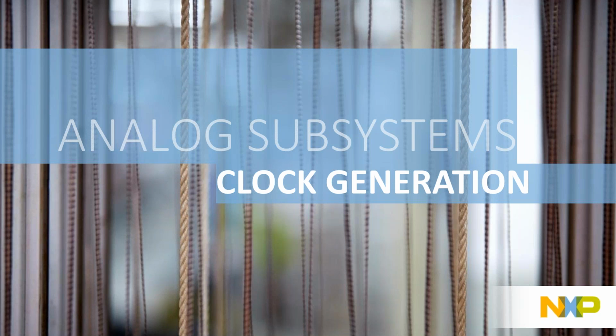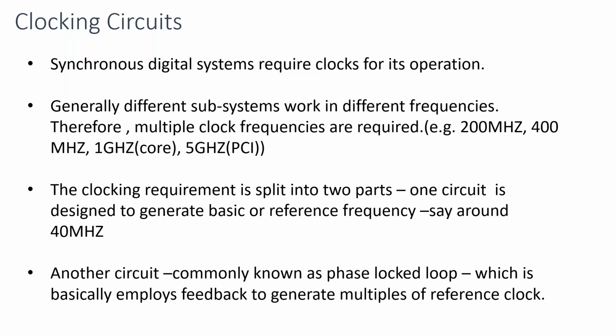Okay, so next I will capture in somewhat brief detail the typical analog subsystems which we work on. We'll start with clock generation. If you see most SoCs, you need multiple clocks. The core works at 1 gigahertz, maybe IO works at 100 megahertz or so, and there will be some subsystem within the SoC which will work at, let's say, 400 megahertz. Depending on the protocol and how it is working, you will see multiple clocks, so you need to generate multiple clocks.